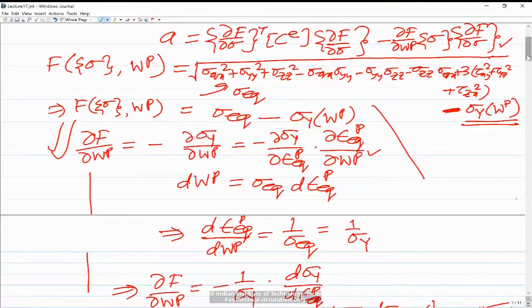Sir, how do we find alpha? We had discussed that one of the simplest models to find alpha is Prager's rule. So we calculate the incremental plastic strain, and then d of alpha xx is c times d of epsilon xx p, and that kind of relations. So we calculate the incremental back stress alpha, and then add it to the previous value and get the total alpha.